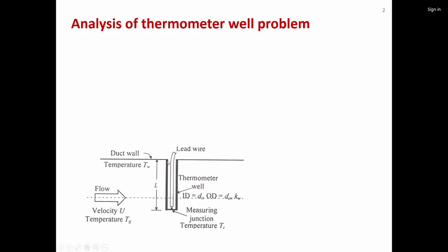Okay, if you did not introduce this tube here, you would have gotten only this much area for heat exchange between the fluid and the thermocouple. Now, by doing this, the heat exchange surface has really enhanced. Now, you introduce the thermocouple like this, and you measure the temperature of the upper surface of this cavity here, somewhere here.